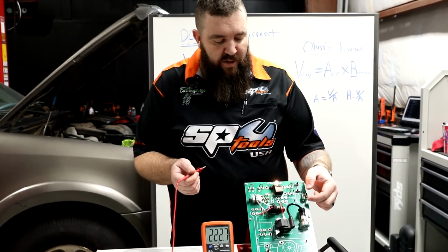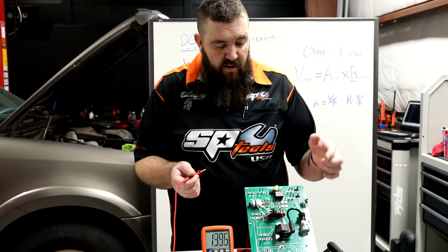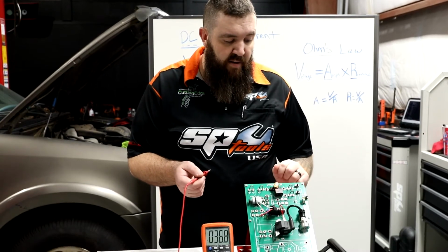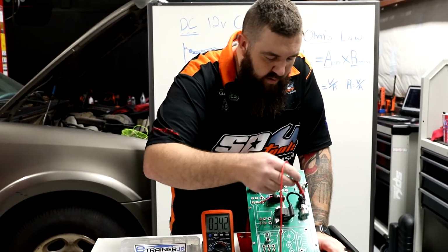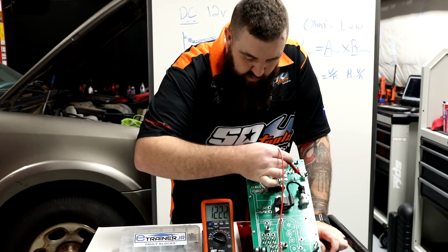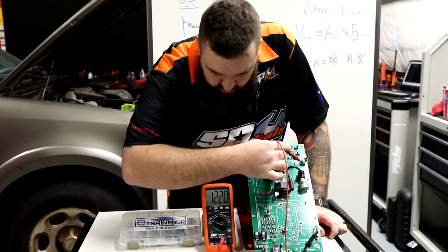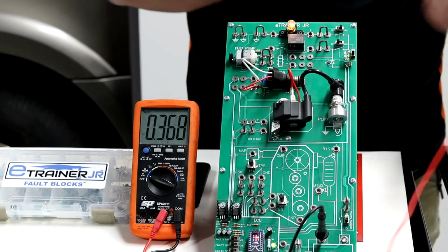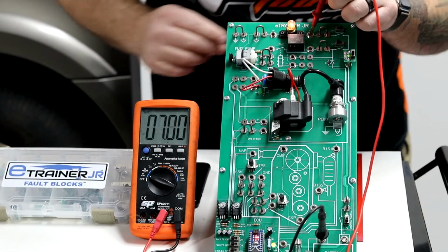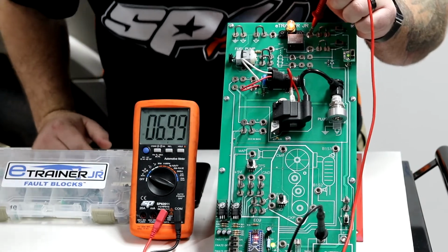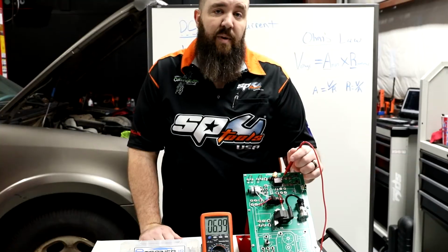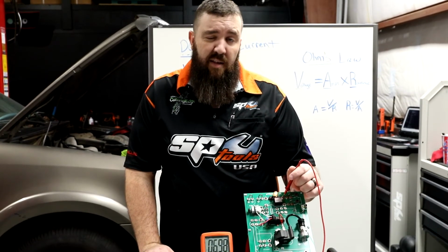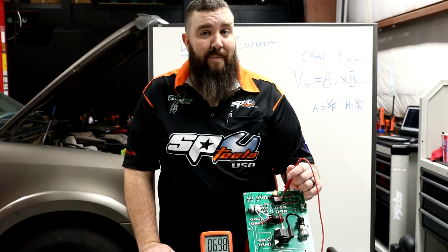So now that we switch our resistor on, we can see our light bulb dim greatly. Just before the resistor, we can see our voltage value is still at 12 volts. Now after the resistor, we can see that we've dropped all the way down to 7 volts, and that's because we added that extra 40 ohms of resistance. Let's go back over to the board to show that math-wise.